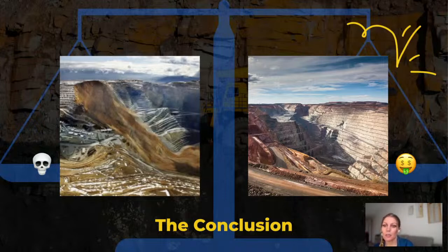In our case, increasing the angle by 3 degrees allowed us to reduce cost by minimizing the excavation of overburden, which is 2.5 million tons less, and obtain the same volume of minerals. It also enabled us to extract more minerals and extend the life of the pit and the enterprise as a whole, an additional 3 million tons of ore.